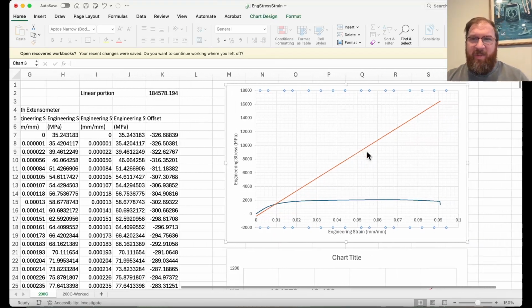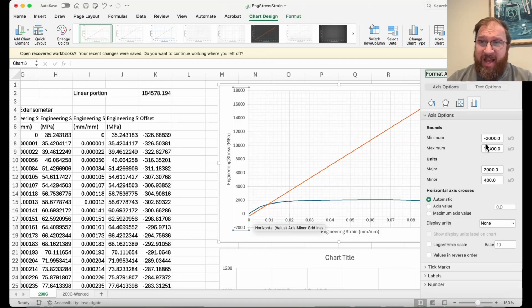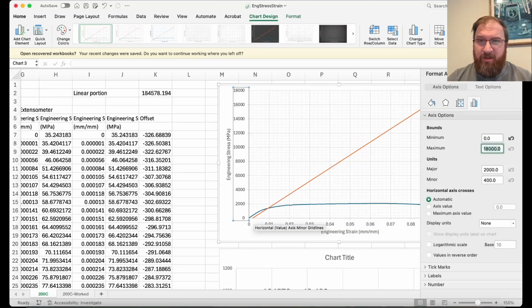It might look a lot different, but that's just because we are plotting a lot more data than we actually need. So if I double click on the y-axis, I just want to go back to 0, because anything negative doesn't matter. You see it plots a lot of extra data, so I'm going to rearrange the y-axis.